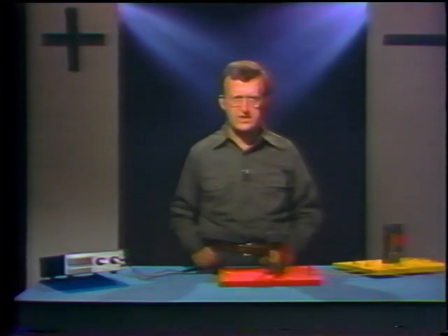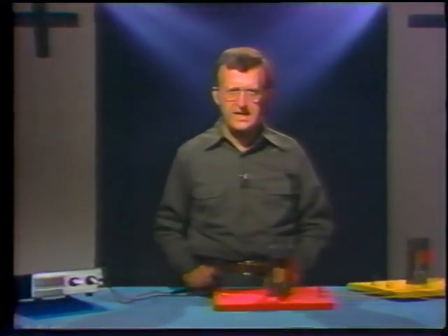The formula works when a transformer increases voltage too. For example, suppose a transformer has 10 primary turns and 30 secondary turns. In the formula, N sub P becomes 10 and N sub S becomes 30. If the voltage applied to the primary is 10 volts, E sub P becomes 10. This time when we work out the math, we see that the secondary voltage, E sub S, is 30 volts. When the secondary winding has 3 times as many turns as the primary winding, the secondary voltage is 3 times the primary voltage. We'll be going into more details about how transformers work in the next segment. Right now, though, why don't you read through segment 1 in your text and make sure you understand what we've covered so far.